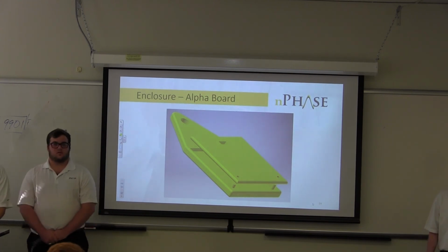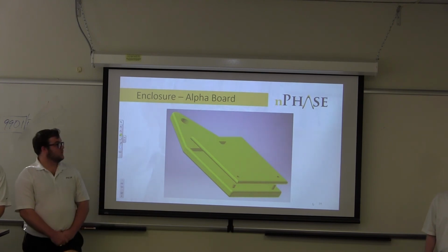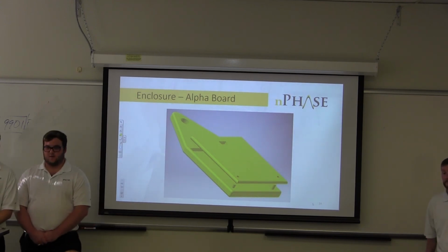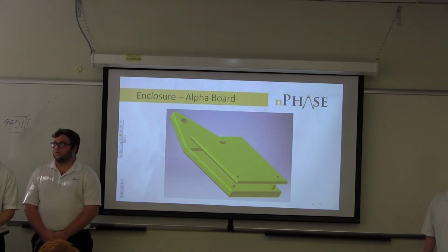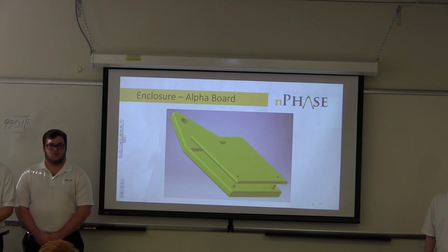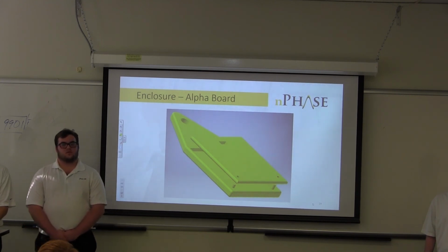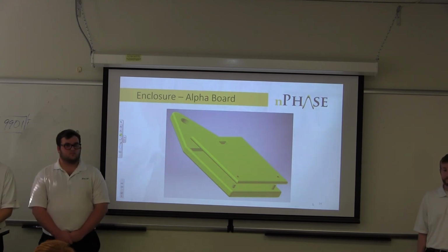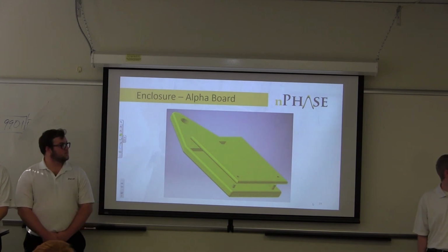How far away is the temperature sensor in the cow's ear from your board? Is it connected through a cable? Have you tested if the signal is messed up anywhere? There is actually specific cabling for our temperature sensors. It's a twisted pair with some special shielding on it that is made to deal with those kinds of issues. Are these meant to last a very long time, or are they more meant to be somewhat easily replaceable if they are damaged? Somewhere in between, probably. With the one month battery life, we assume it should at least last that month. Right.